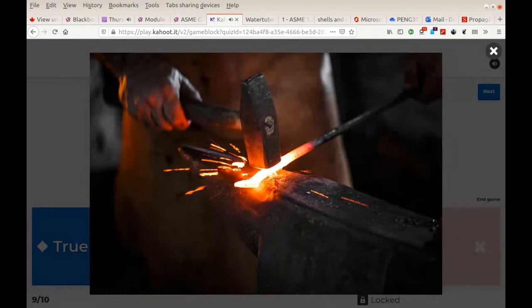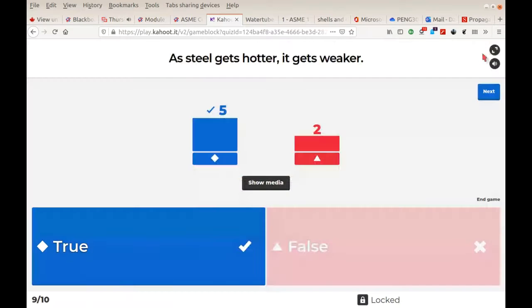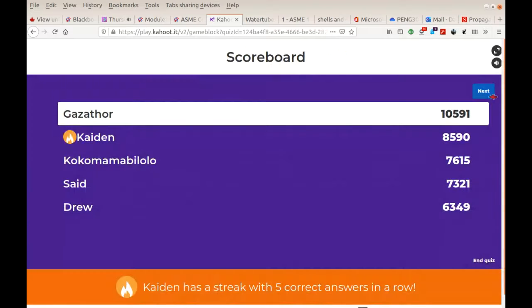Yes, so that's why the blacksmith has that poker red hot so that he can form it into whatever shape with a compressed force relatively easily. And so how this works in the boilers is the hotter the component, the weaker that it gets, and we see that with ASME 2D. So that's why we need to know the stress or strength at temperature.